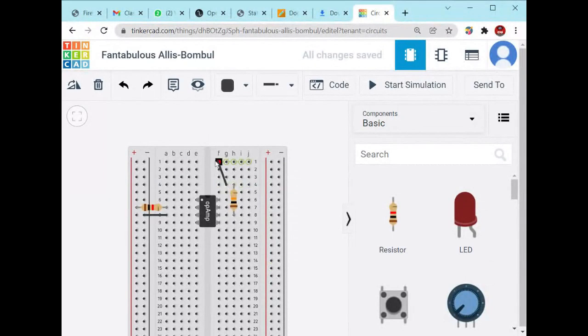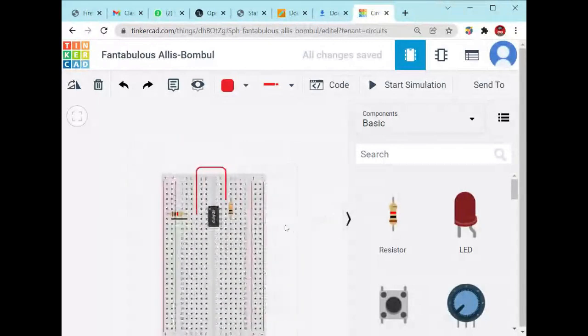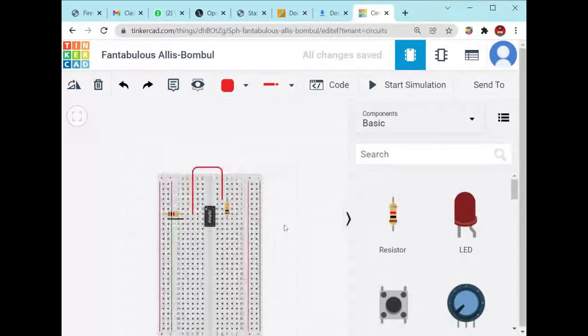This connection should be connected to the input and change its color to red, because this is a positive connection. Here is the inverting input and you have connected the output also. Now you have to select the power supply, function generator, and CRO or digital oscilloscope.